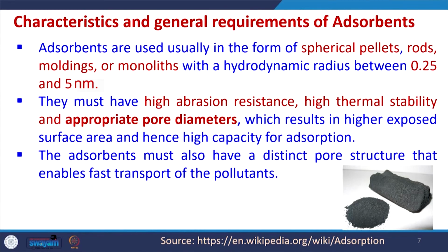They must also have high abrasion resistance, high thermal stability and appropriate pore diameter. The thermal stability criteria is more important for gas phase separations, because the gases may be at higher temperature. For liquid cases, for water or wastewater treatment, the temperature is not that important, but abrasion resistance may be important for those waters which may be highly acidic or highly basic. So, under those conditions the adsorbent selected should be chemically stable also, and that is one of the important features we always look for.